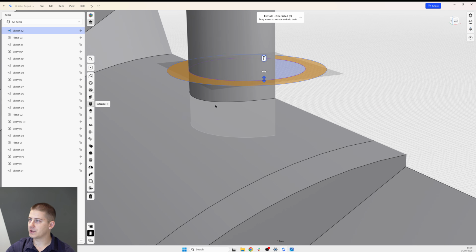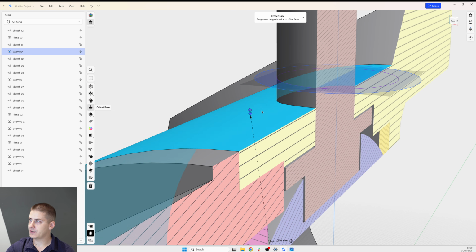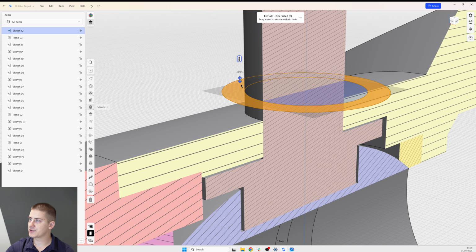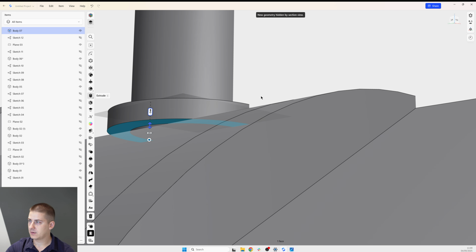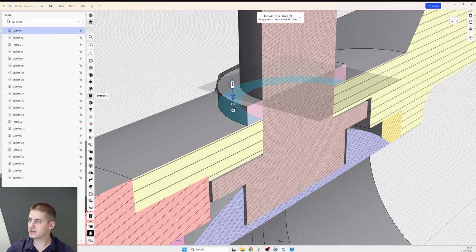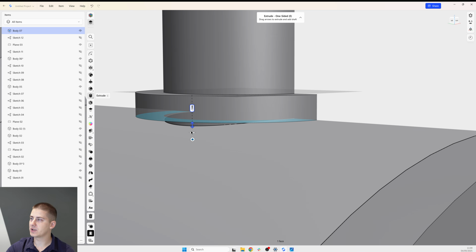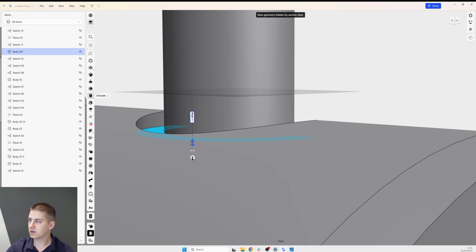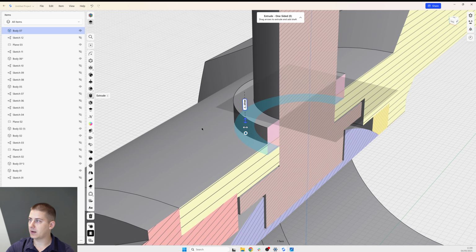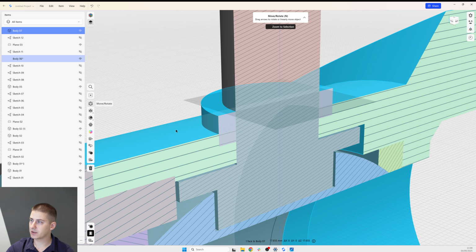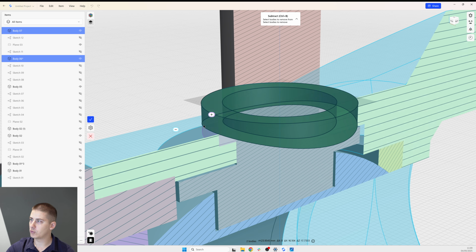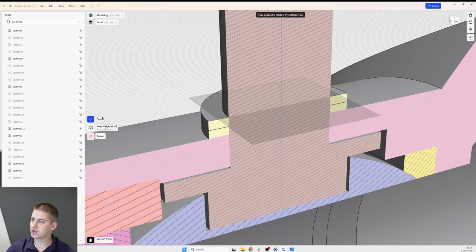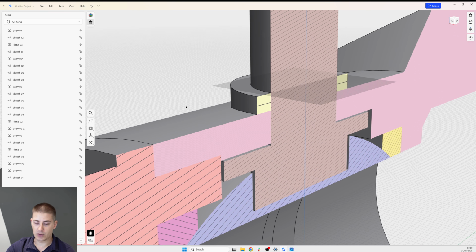the key thing to notice here is that this face is curved, so the regular extrude feature would not work very best in this case. I mean, we can use extrude feature, we can create new body and extrude it a little bit more, new body, and now with subtract feature we can remove this bottom body from it, but we also want to keep this body. So that's the one way.